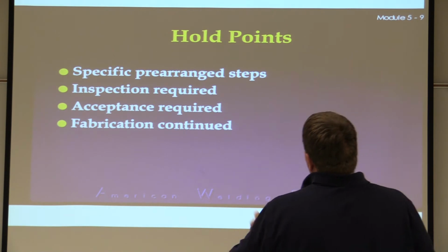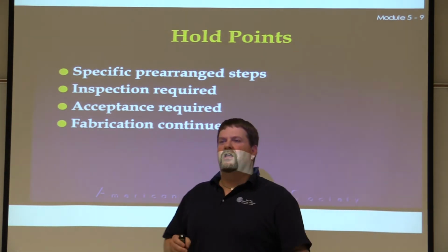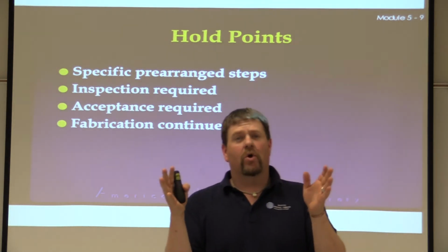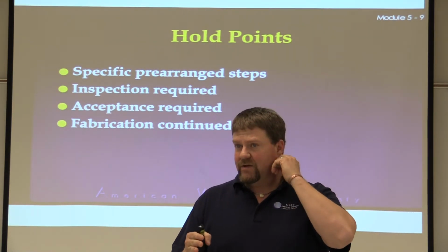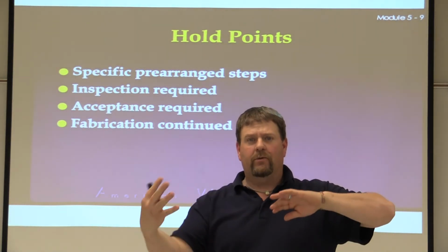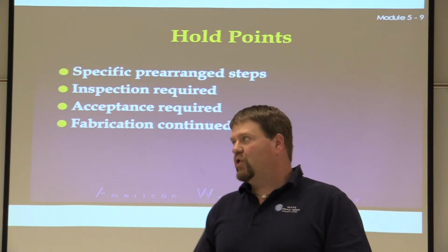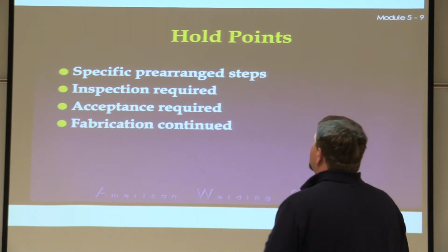After that, then you can weld, usually say, put the root pass in, and then I want to see how much it's distorted. It might be another piece, okay? If it's warped or bowed or anything else, that might at that point be a point for rejection or to get a piece out of there.